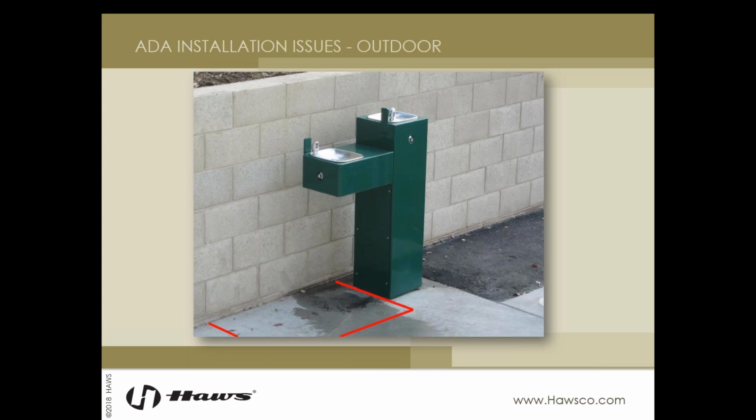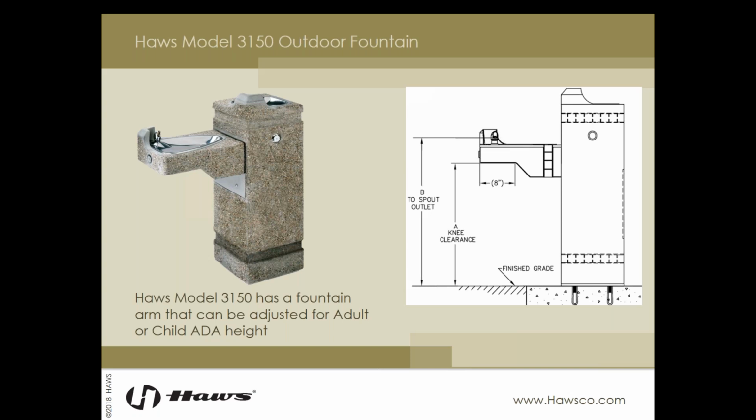We may only be off a couple of inches, but remember that close enough doesn't really cut it when it comes to the ADA. If a field inspector were to find this, they could force a tear out and reinstall, which could be costly, time-consuming, labor. All of those things would be factors. So we need to make sure that we're paying attention to accessible design.